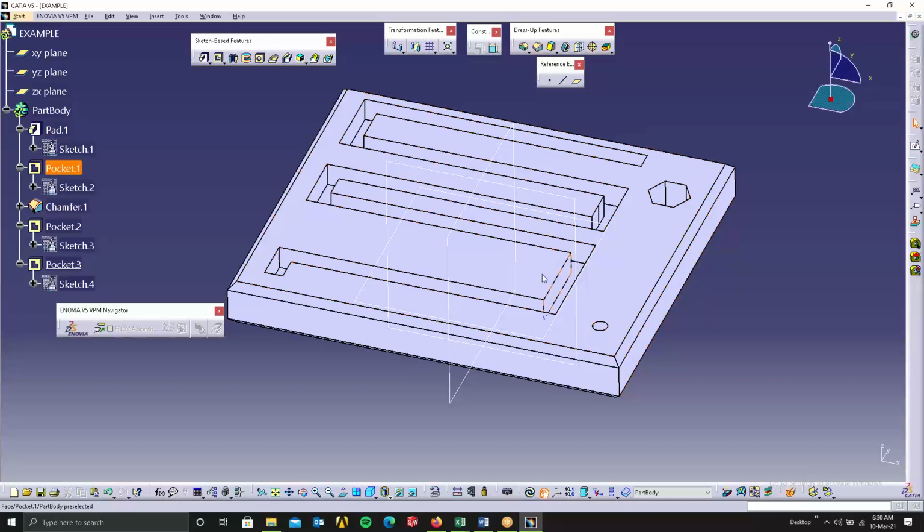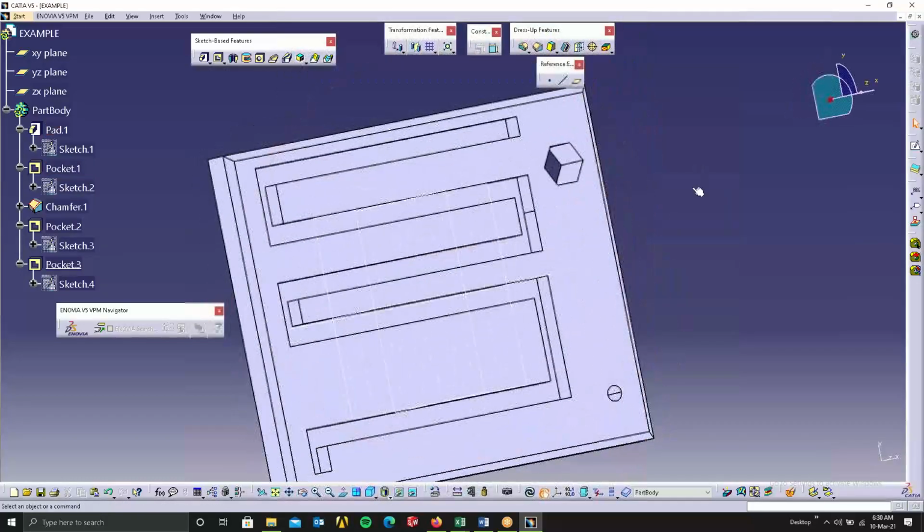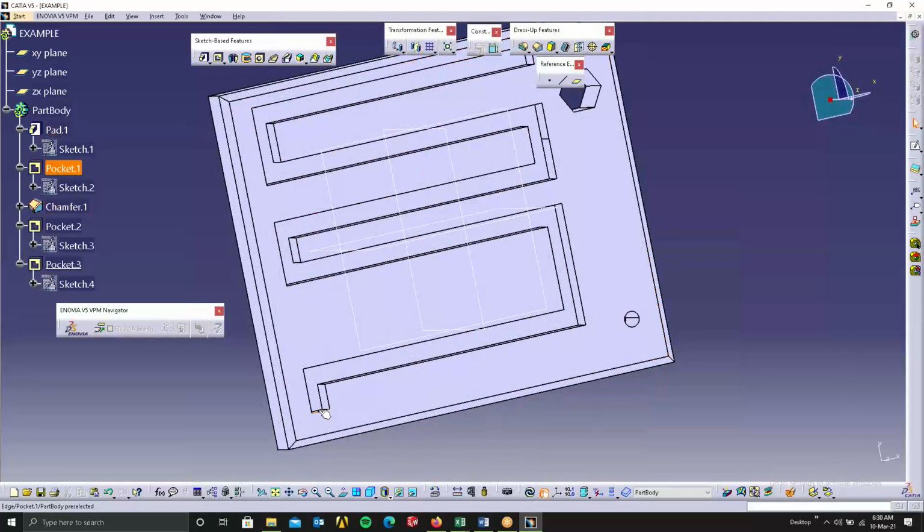Just imagine the tool which I told you, 7,200 RPM. It's rotating, be it rectangle, be it square, be it anything. If it's rotating at 7,000 RPM, it's going to create a big circle, right? So this tool is coming at high RPM, coming down. When it's coming down, how are you going to get the sharp edges? Using a rotating circular tool, can you create these sharp edges? It might be difficult. It's not difficult, it is impossible.